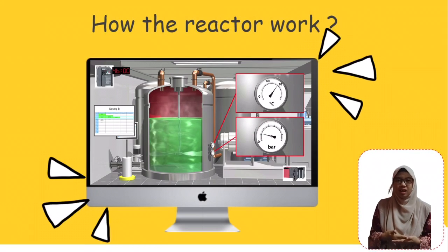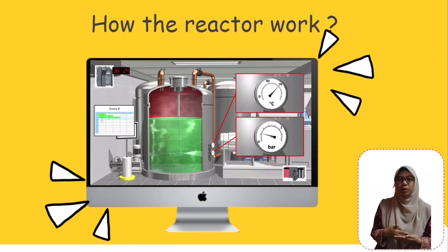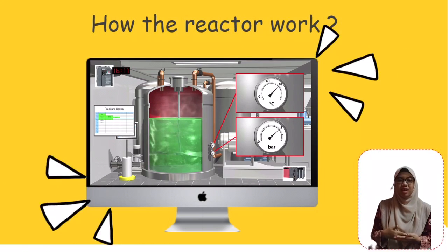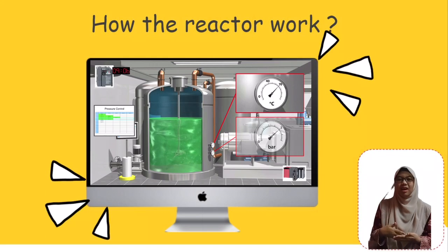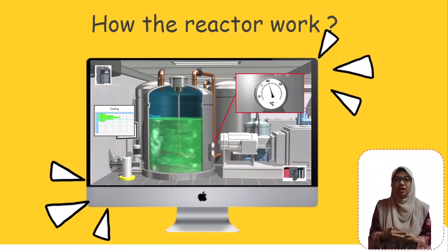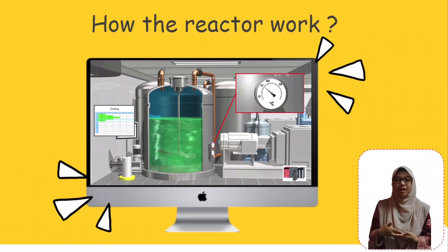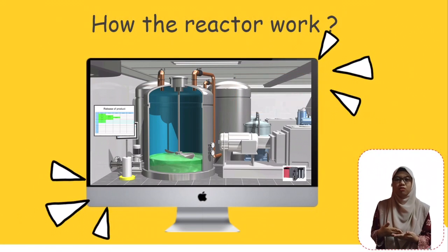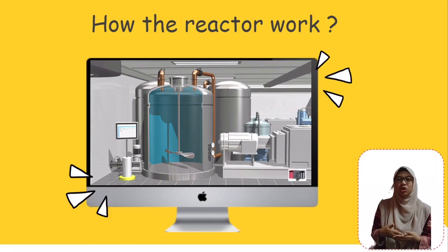Following reaction, the reactor is cleaned to prepare for another batch of reactants to be added. After that, the products and unreacted reactants are removed, and the process is repeated. In this situation, batch reactors contain ports for injecting reactants and removing products, and can be outfitted with a heat exchanger or a stirring system.